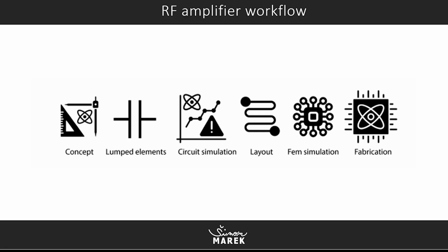You might skip the part of lumped elements and circuit simulation by just following some guidelines from a datasheet and some application notes. So you might abandon the circuit simulation and go straight to layout, but it really depends on how advanced your design is.